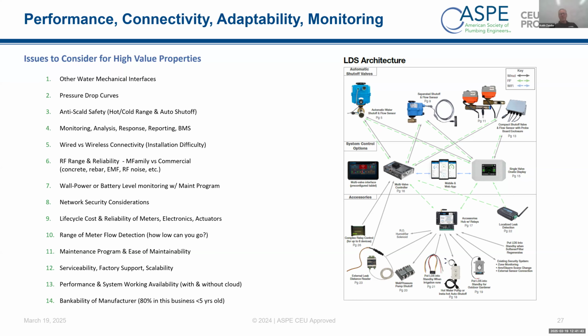And water detection systems. So if the system goes into alarm, the valve shuts off, and then power goes off. When power comes back on, it's good to know your sequence of operation. When power comes back on, what happens? Well, if it's in alarm, we've got non-volatile memory in there. It knows it was in alarm. It will not do anything. It requires manual intervention to turn back on.